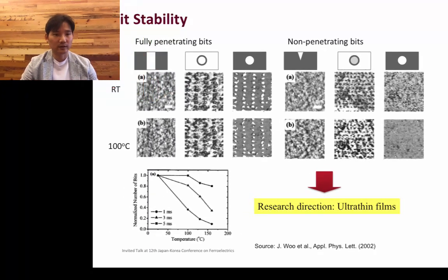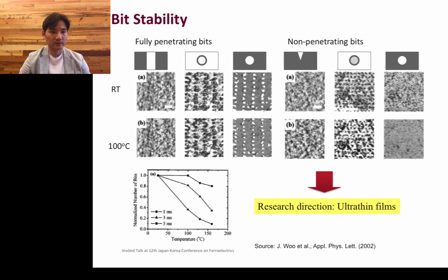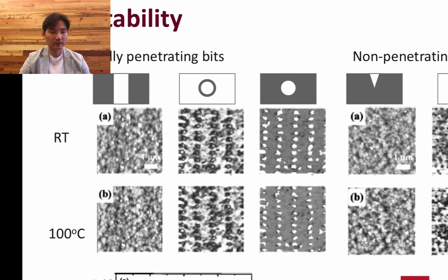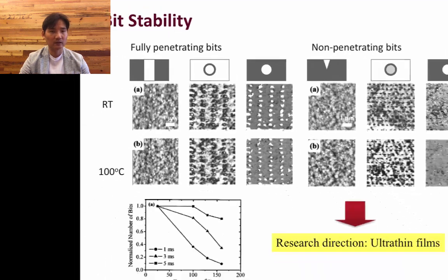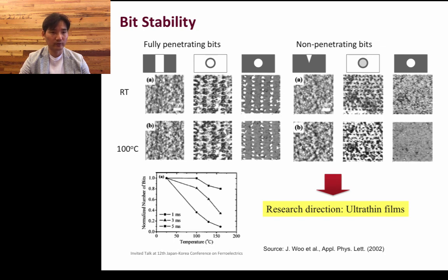We also did a lot of work on bit stability because people were worried that, unlike in magnetics, the polarization formed by electric field may backswitch and you will have loss of memory. So we understood that charged dipole interaction is very important, and fully penetrated domains are the key to stabilizing the information you have written in your ferroelectric media.